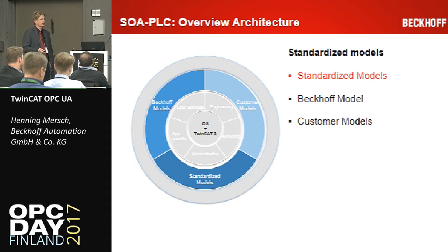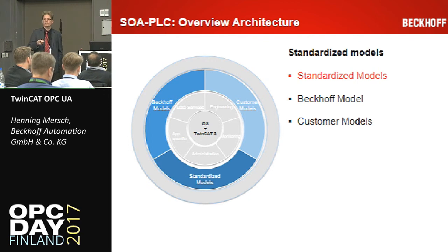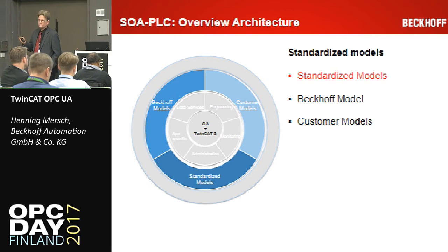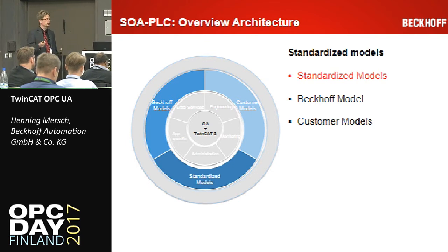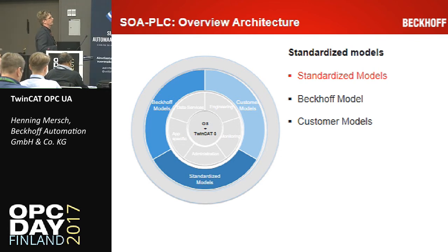The other one: we think there will always be vendor-specific enhancements because the different vendors would like to have unique features, right? And to have innovations, you need to have the possibility, and luckily OPC UA provides us with the ability to provide another model in addition. So we could provide a companion specification which is accepted in a domain, and additionally provide additional features for our controllers or for our machines, if we are talking from the point of view of our customers.